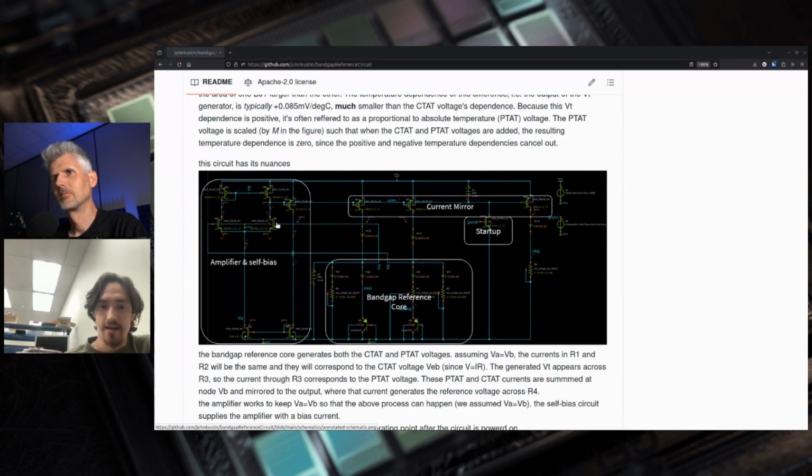It's negative feedback that allows us to force the error between VA and VB to be very small, very close to zero. If that happens, then we should have a working bandgap. And that should work on another wafer with slightly different sized transistors. Yeah. As long as all these devices are close to each other on that different wafer, you're good. I think that's probably how people are able to make the claim that these circuits can be put into mass production and have high yield.